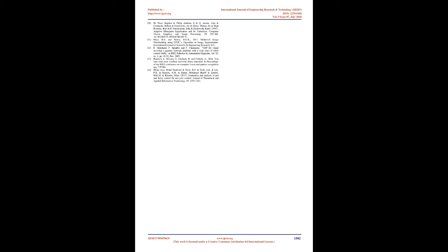Emphasis has been laid on the external manipulators to accomplish the required tasks. Power management and transmission play an important role in determining the endurance of any AUV, and hence strategies have been implemented to make it effective. Failure of the AUV due to power supply shortage via battery is prevented by switching the power lines to another spare battery placed in each of the battery canisters. Inrush current is also reduced through a custom design board.